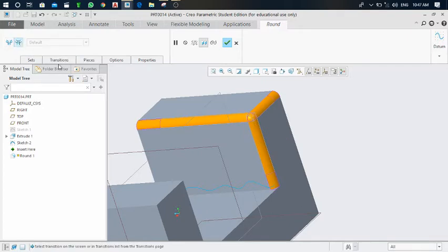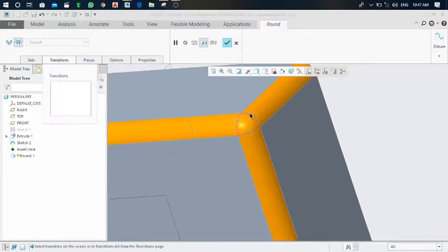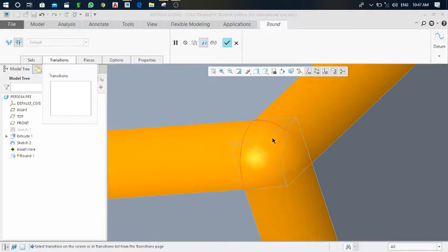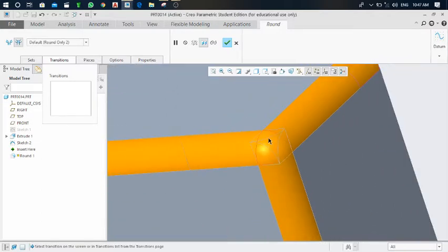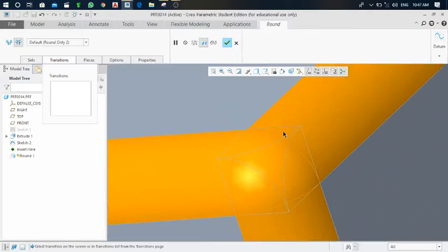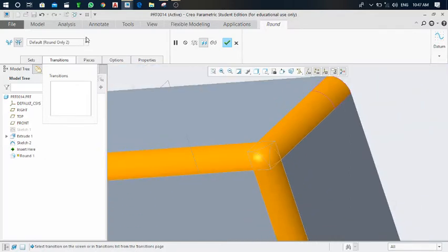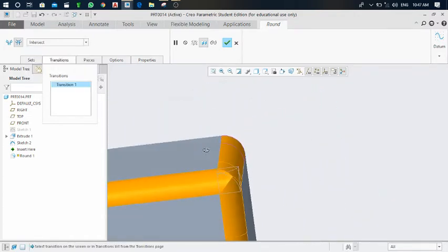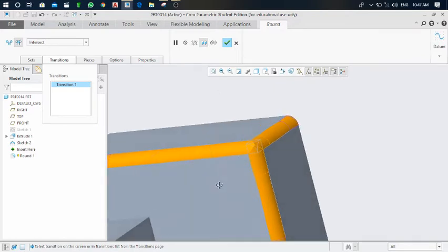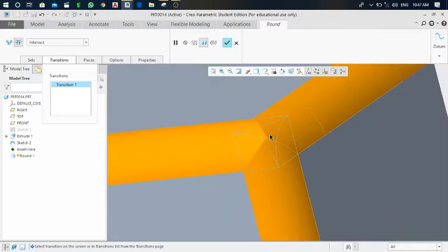Okay, and next here, this is the intersection point. If you select this intersection point, this is highlighted over here, you can see. So here some options will be visible or created like this. Intersect, so this will change, it will convert into intersects like this. Here you can observe. So go here and click on this corner sphere, so it will convert into corner sphere.